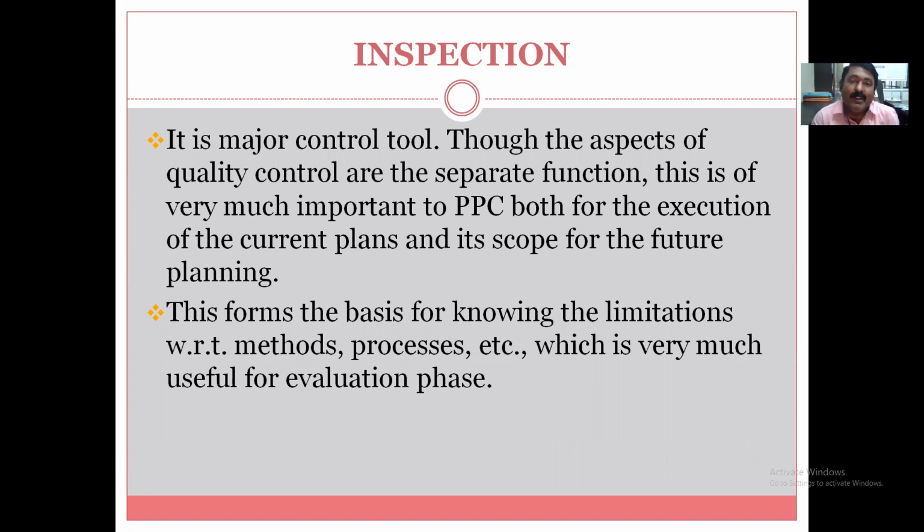For example, if you are drilling, the worker is using a jig. The jig is inspection and quality control checked, and the operator's job is just to put the job on the jig and go for drilling and process the next. Now, if the jig has some error and the error is translating, or becoming cumulative, so that more error will be there in that drilled hole, again it is neither the fault of the machine nor of the operator, because it is there due to the jig. Just an example I am giving.